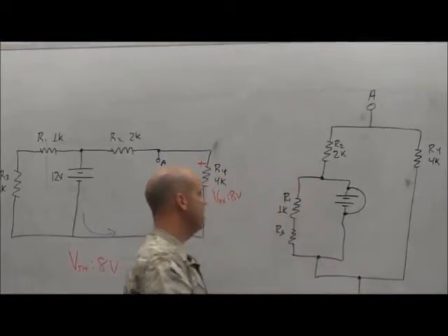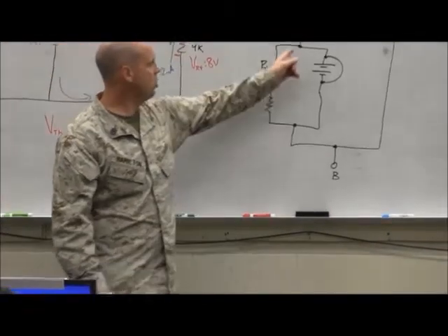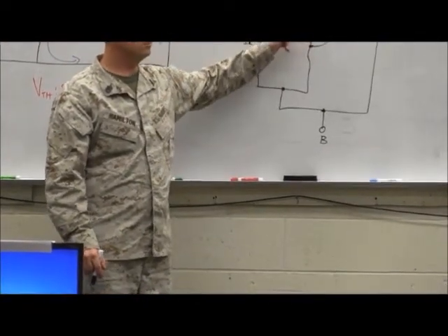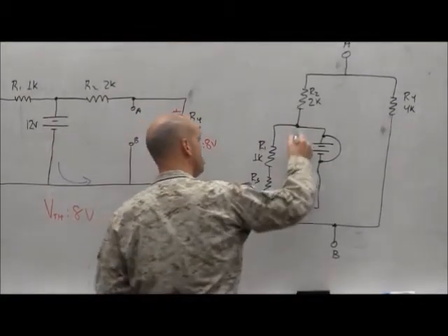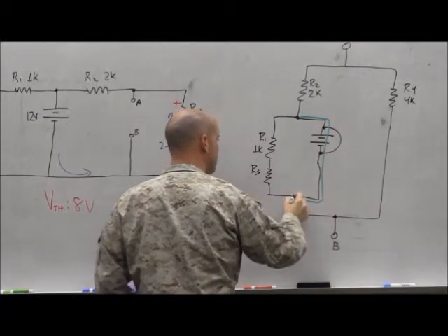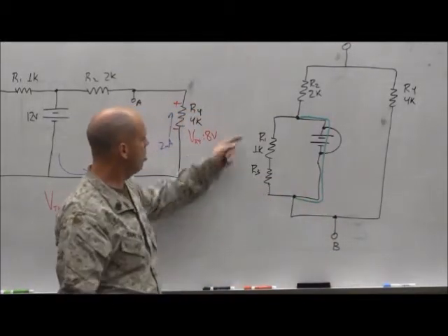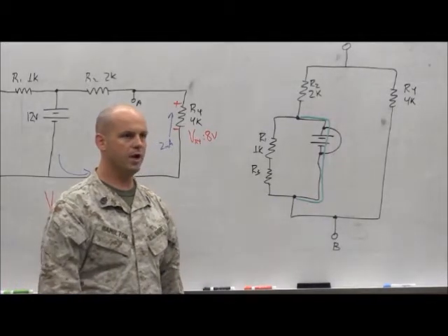All right, let's add up our total resistance. This is a short through here, is it not? If this is a short, this is a short along this path right here. Will this R1 and R3 come into play at all? No, they will not.